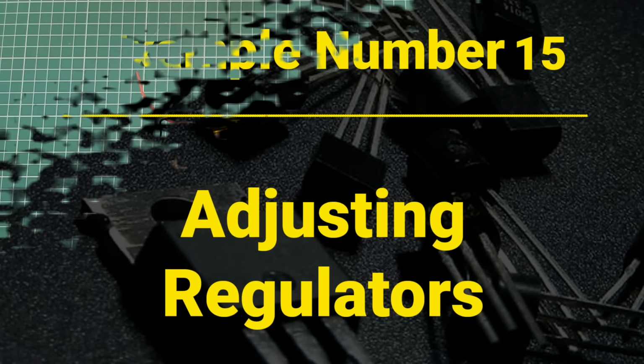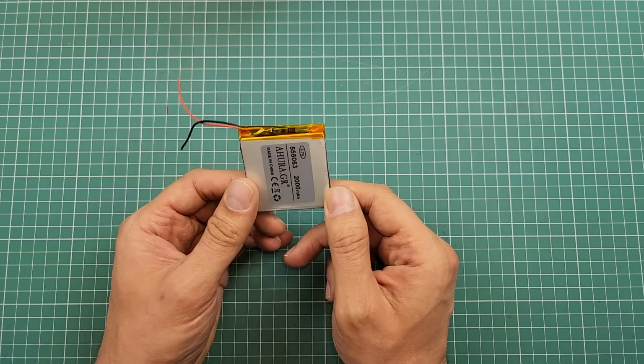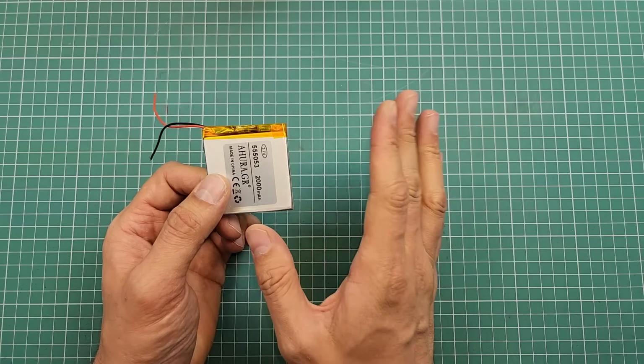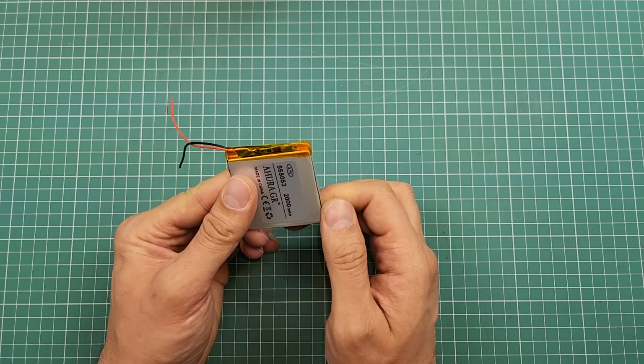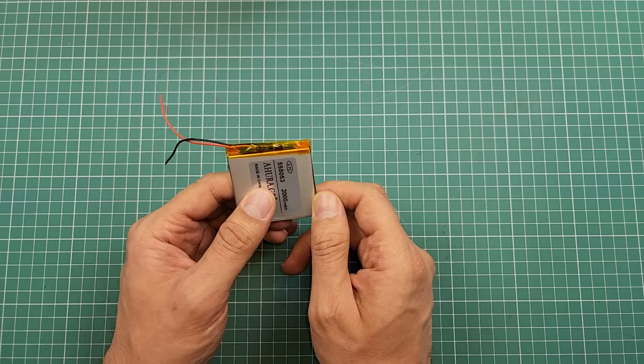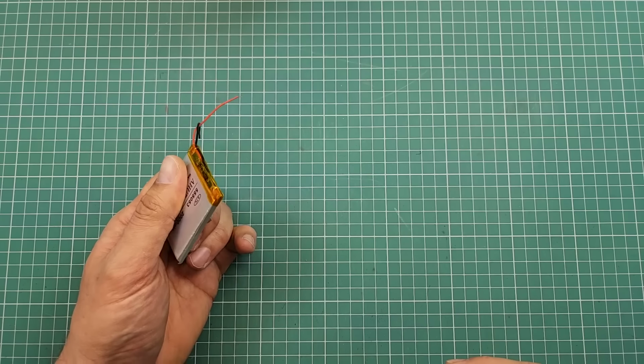The next example I'd like to delve into is the role of resistors in adjusting an adjustable regulator. By referring to the datasheet of any adjustable regulator, we can find some resistors that are used to determine the output voltage. Example number 15, adjusting regulators. To charge these batteries, we have to make a proper voltage, say 4.2 volts. Since this voltage is not a standard voltage, we need to regulate a higher voltage to 4.2 volts. There are numerous regulators to use. LM317 is one of them.